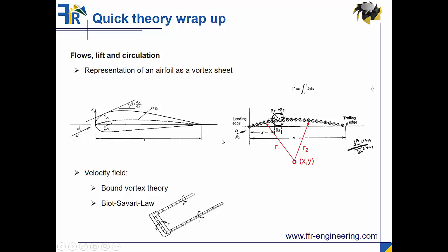And then from the Biot-Savart law, which is also known from electromagnetism, you have the relation that if you have a point in space, given x, y, and the distance and direction to the set of vortices... You might know the Biot-Savart law from looking at only one vortex, a singular point, but here we have a sample of vortices, and what you have to do is look at the contribution of each of those vortices to the velocity field at the point of observation. Each of them has an influence here.